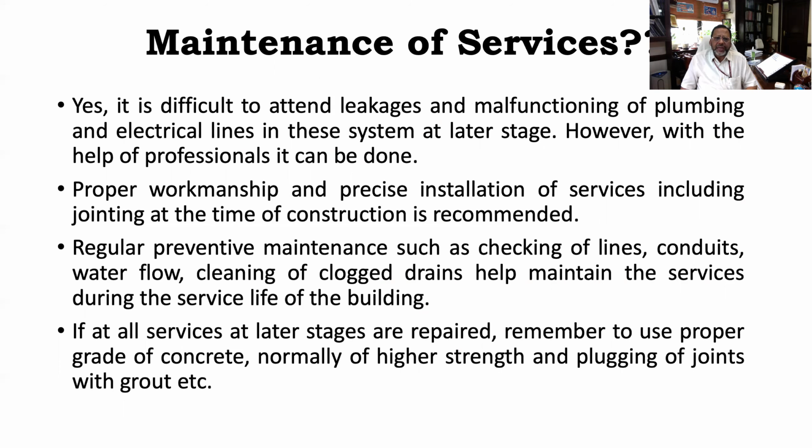But as regards maintenance of services, it is always advisable to have regular preventive maintenance of your structure. Regular preventive maintenance means that we should regularly check the sewage lines, water pipelines, other conduits, and water flow. We need to clean the roofs before the onset of monsoon.